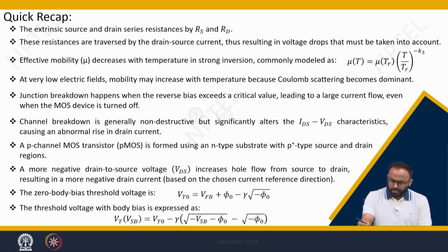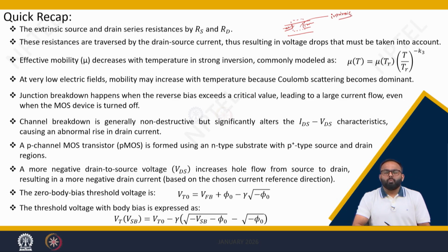In the previous lecture, we discussed that we need to consider the extrinsic effect while modeling the device. This black box is only concerned about the intrinsic part, which governs depletion, inversion, gate charge, oxide charge, etc. However, the overall performance of the MOSFET is given by intrinsic plus extrinsic effect.